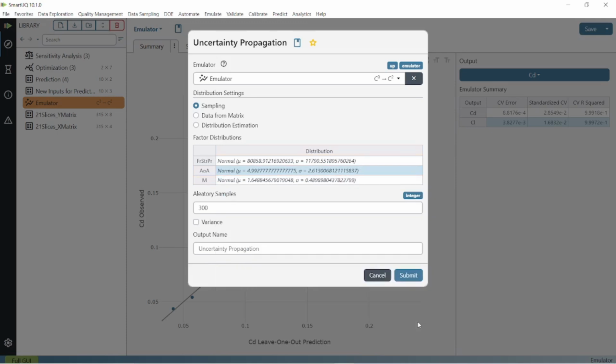The next step would be giving the number of simulation runs. Here you have to specify the number of simulation runs, and this uses the Monte Carlo method. The Monte Carlo method randomly samples the data points in your design space within the input and output bounds that you would have given, and uncertainty propagation requires a large number of simulations to be performed. For example, I have three input parameters, so I'll be giving 3000 simulation runs. I can even give 30,000 as well.